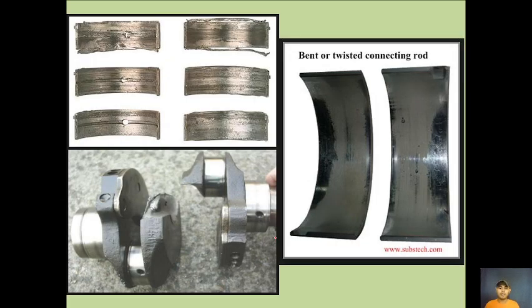Okay, so bearings could be damaged like this one. A slight discoloration or a scratch on our bearings, you should check the problem and replace the bearing already. Don't wait for the bearing to be damaged like this before you replace it, because it's a very big problem if the crankshaft is damaged. The one that protects the crankshaft from being damaged is the bearings.